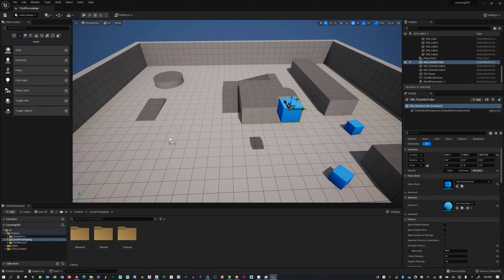Now if you are moving, the other thing is sometimes this works, sometimes not, depending on the collision. If you hit the End key, that should force this to drop down to the lowest thing that it's going to hit. So if I have it above this here and I hit End, you can see it's going to throw this on top of that, like that.